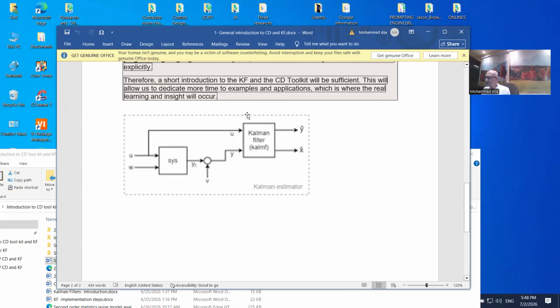So Kalman filter, which is designed by LabVIEW, has two inputs. The first input is the input fed to the control system itself, and the other is the output of the control system, which needs to be treated to get an idea about the more accurate instantaneous values, estimates in other words, of the variables in this control system.